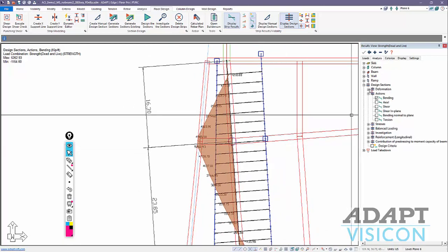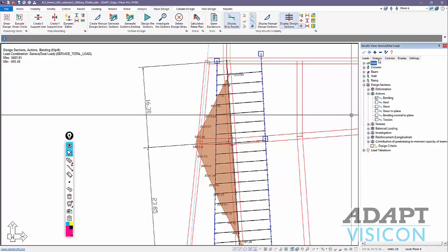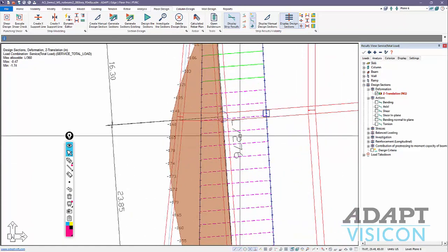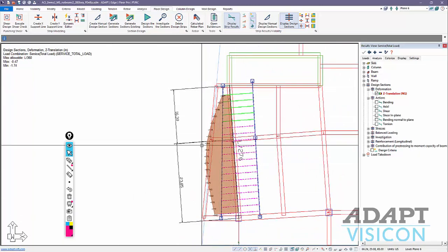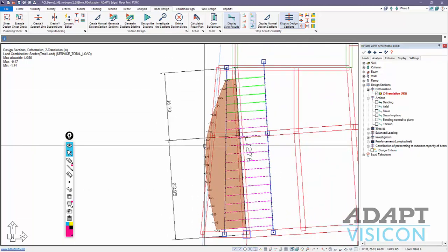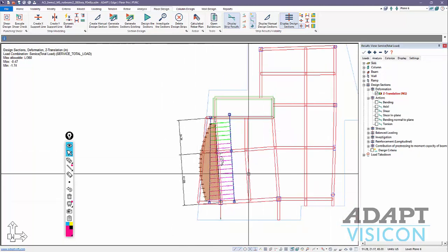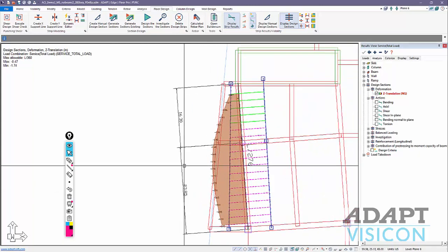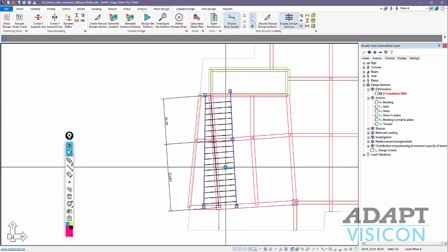We can also check, for example, deformation. If we go to a service combination, service total, we might want to check the deflection along the beam. So the deflection is L over 276 for this full span, and these are just integrated deflection values over the design cuts. These are not long-term nor cracked deflections. We would likely want to run this entire floor for cracking, and that's illustrated in a different tutorial video that we have. So again, we're just defining the different workflows here. Okay, so that's workflow 1.